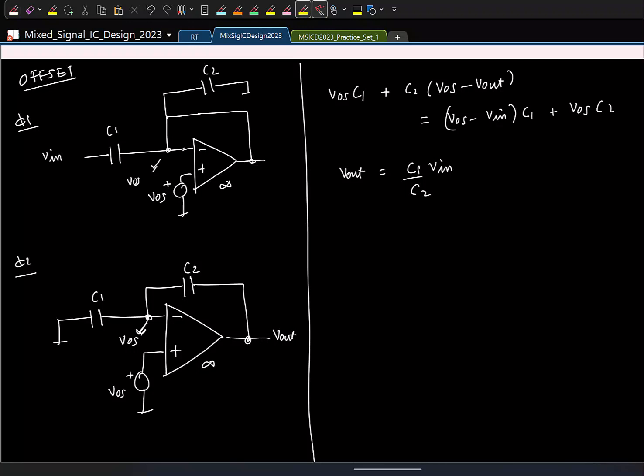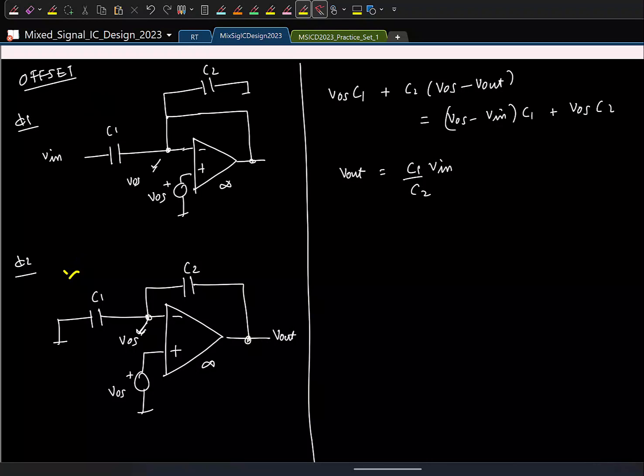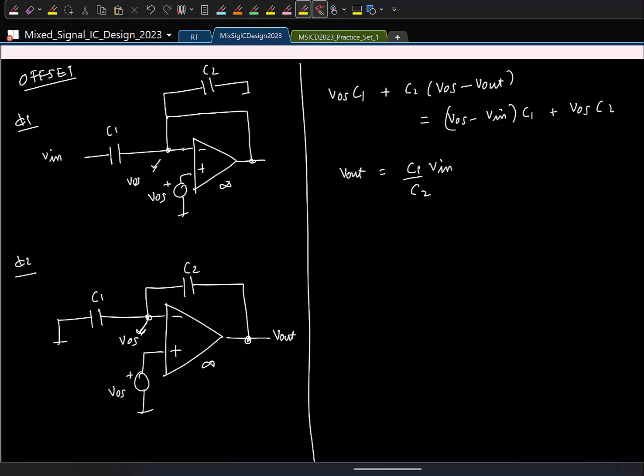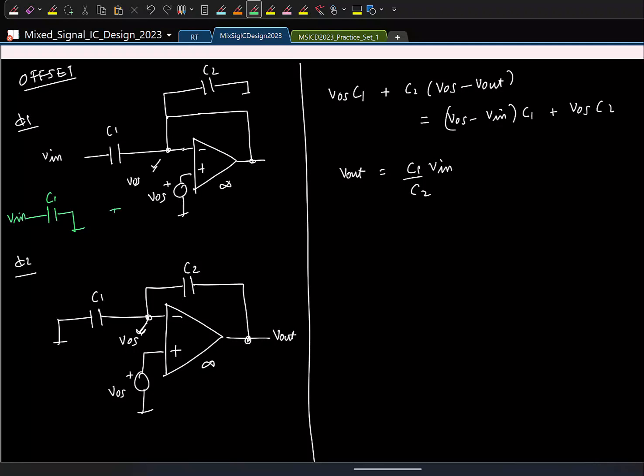I mean, the circuit operates in two phases, right? You look at the two circuits in the two phases, and the charge stored in C1 is not V in C1, but it's V. Basically, the circuit is different only in this phase, right? In phase phi 2 it is all the same. The only difference is here, and in phase phi 1 normally what do we do? We charge the capacitor to V in, C2 is fully reset.